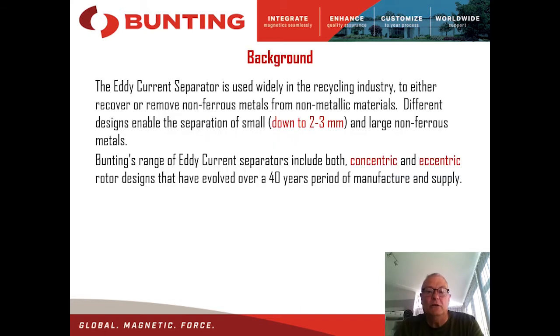So a bit of background on the eddy current separator. They are widely used in the recycling industry on numerous types of application for the last 40 or 50 years or so. They're used to recover conductive materials from non-conductive materials in waste streams, so for example plastic from aluminium. Different designs are on the market which enable separation down to a particle size in the range of 2 to 3 millimeters in size.